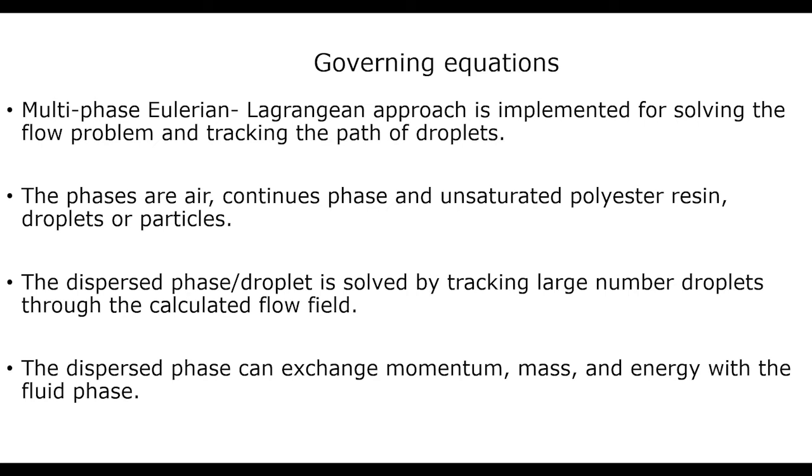So this model is solved by tracking a large number of droplets, just tracking each droplet in the flow field. So there will be an interaction between the droplets and the flow field. So there will be a mass, momentum, and energy exchange between the particle and the fluid. So the process will consider all these things.